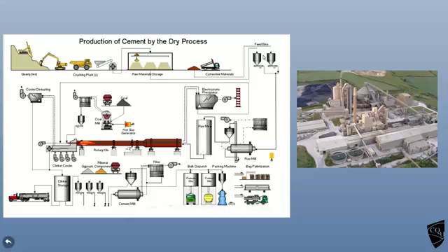They go into feed bins, carefully controlled how much comes through. Goes into the raw mill. This is the rotary kiln, that rotates and keeps it mixed up, and it's hot. Then it comes out as clinker, and they cool it down. And then the clinker gets stored down here. Now you can take the clinker away, or you can put it through a mill and crush it up, filter out the bad bits, and then store it in silos to be sent away. No water added at this point, that's added just before you use it, okay? So it's quite a simple process, really.